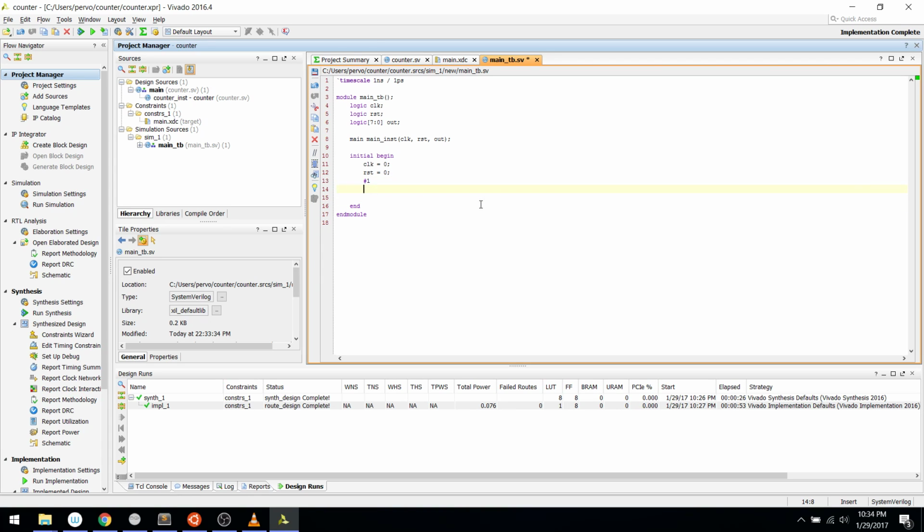This simulation, by the way, doesn't really use all the timing constraints. So you can just do it in internally consistent units that don't necessarily have to relate to the real clock rate, just a note. So 1 nanosecond is pretty standard for that. So we reset it, and then we wait 1 nanosecond, not 1 cycle. And actually, let me just bring reset high, and then the clock is going to go high with that.